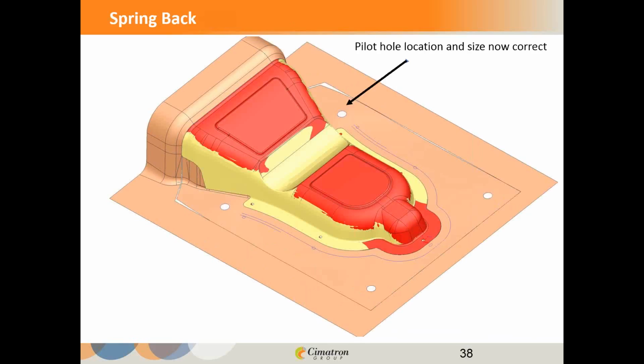You can still see how those part surfaces are being deformed in. It's still taking the data of the part itself, and it's still pushing those surfaces in just like it would. We're just saying don't move the pilot holes. So there's a flexibility there that it gives us where I'm not totally redesigning everything. I really need to know those pilot hole locations, and I really need to be sure they're not going to move. So that's a crucial part in understanding how the die is going to hold its form while I do this deformation.